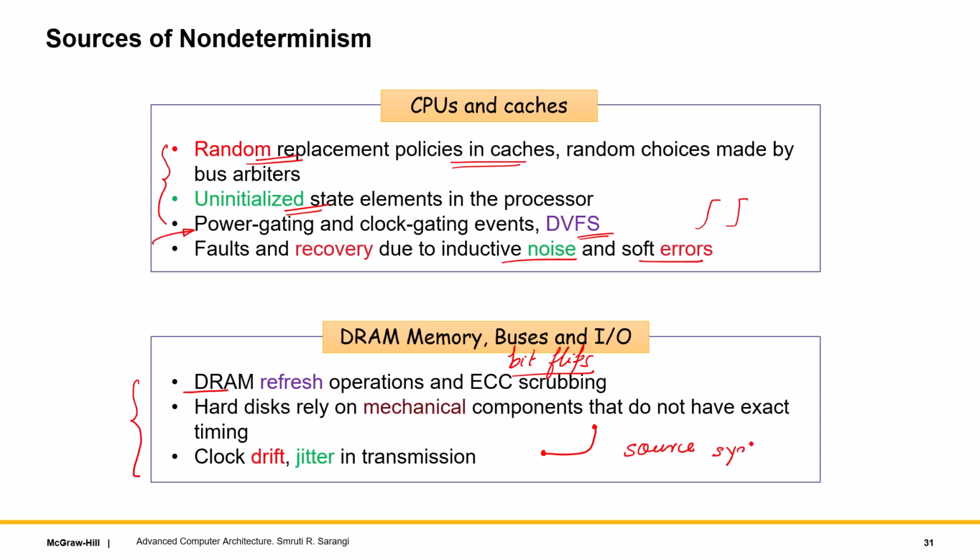A source synchronous bus, along with the data, transmits the clock. So the clock is used to recover the data. Here again, because physical transmission is involved, and also the receiver first has to lock into this clock, a couple of cycles here and there can happen, right? Because latencies are not fixed, they are temperature dependent.